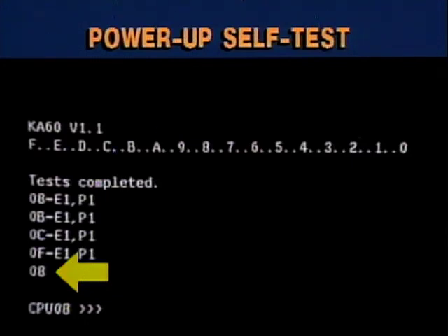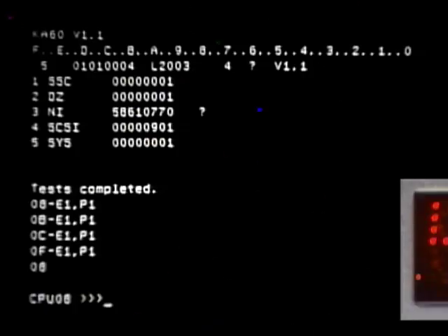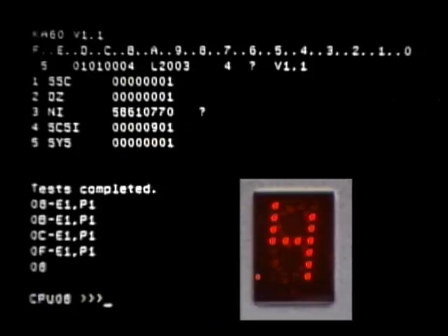The bottom line identifies the primary CPU. This is reiterated by the console prompt. The LED display on the I/O cover module displays .0 upon successful completion. If an error is encountered, the LED display indicates the physical slot number of the module or subsystem in error. If two or more errors occur, the display indicates the board with the highest slot number that had an error.